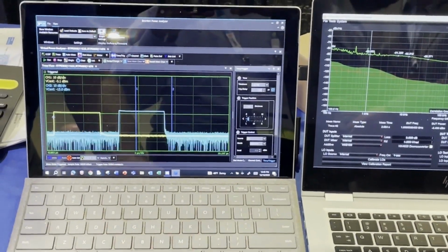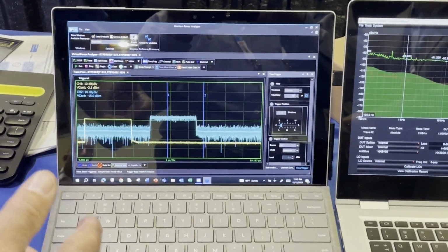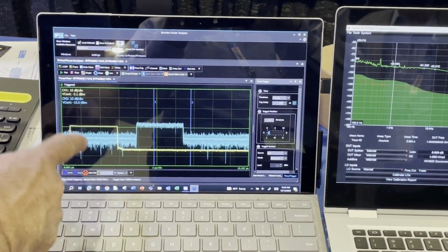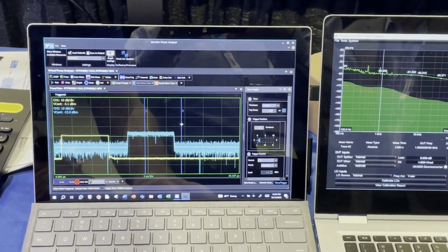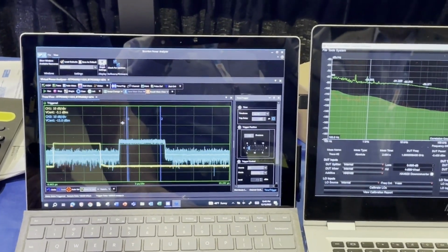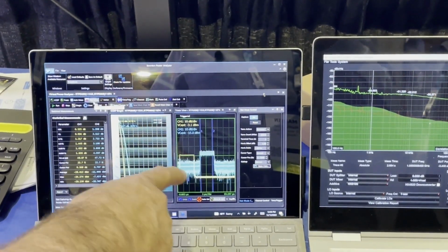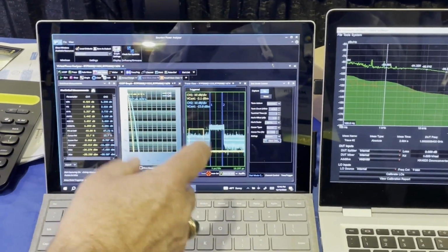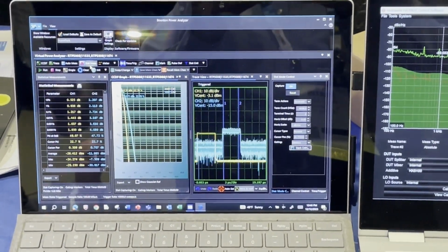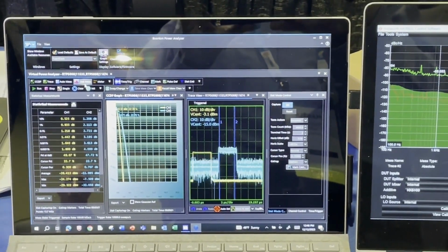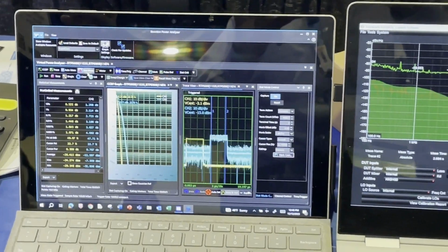I'm going to ask Michael to turn on some carrier to noise for us. And one of the things that we now see is our output actually has some noise on it. I'm able to do measurements of this. I'm able to show on the display the input signal and the output signal that has noise on it, and I'm able to give a CCDF display showing crest factor of the actual signal. And again, this is for amplifier performance.